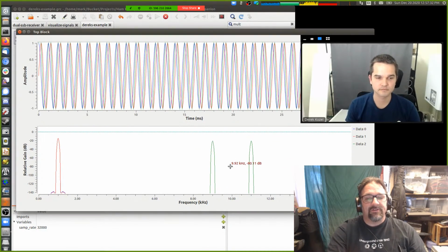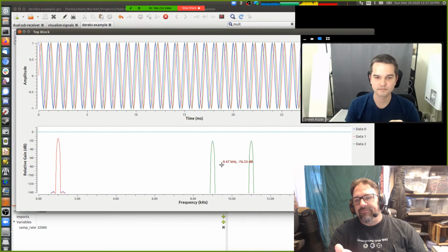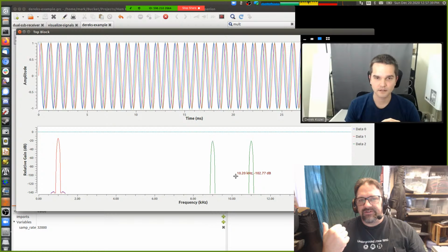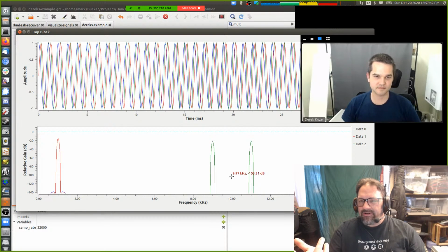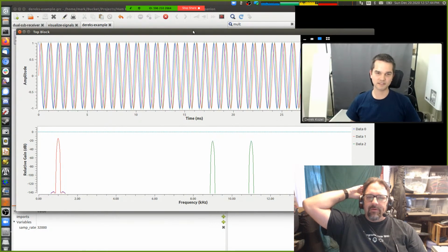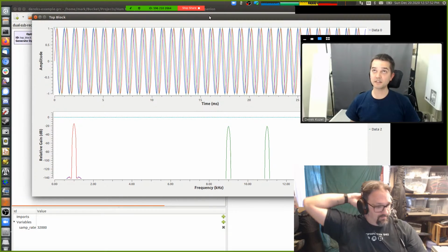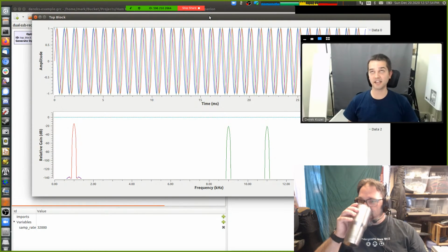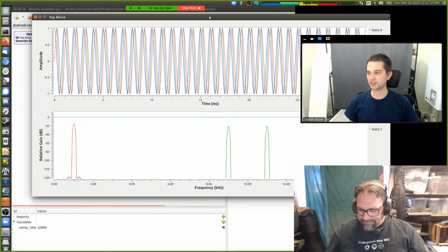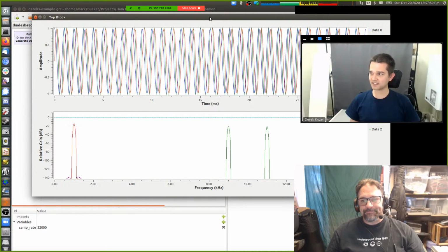That's our AM signal. Although there's no carrier, I never fully understood: is the carrier of an AM signal just leakage through the mixer, or is that something that's added back later? I never fully understood why mixers leak through the actual carrier as well. But leaking the carrier, I think, is a combination of just imperfect hardware. Tim's saying DC offset, which maybe on a physical AM modulator, that's what you get.